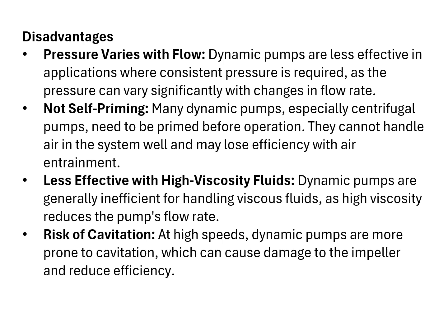The disadvantages: the pressure varies with flow, and it is not self-priming. We need to prime the pump ourselves. It is less effective with high velocity and high viscosity fluids, and the risk of cavitation is high, because since it is a high pressure operation, the risk of cavitation is much higher compared to the displacement pump.